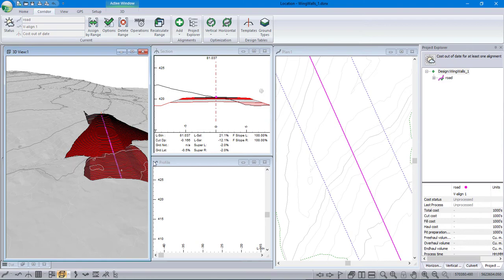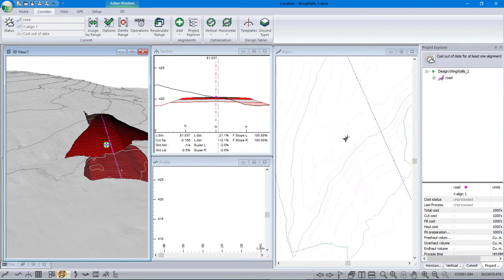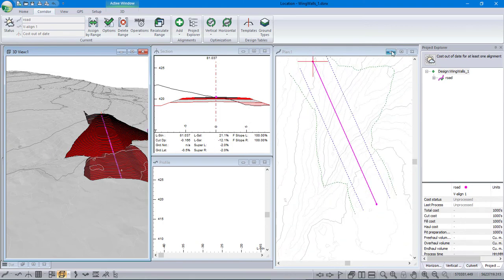And now I'm ready to create a culvert alignment along the bottom. So I could use the culverts tool to add a culvert in the software. That won't give me any options for sub-excavating for the culvert or building wing walls or anything else. It might be all we need for a design, but in this case we want to go a little further.